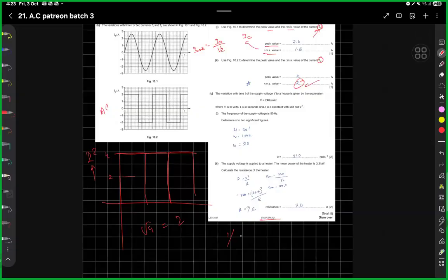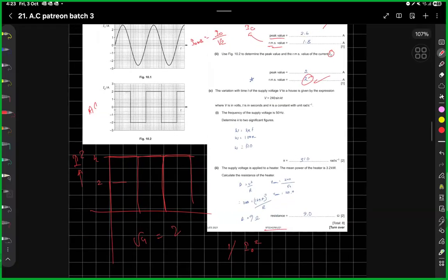So, what was the first step? I find the square values, I naught square. First step is find the I naught square value. What is the maximum current? 2. And that is the only current. That is what is fascinating about this question: there is a variation in direction only and not the magnitude of the value. This is where they put the twist. You're used to this concept, sinusoidal, symmetric about 1 point. This is new to you. It's not exactly new, it's very conceptual, but they are giving you a constant value of current. Forward 2, backward 2, forward 2, backward 2.